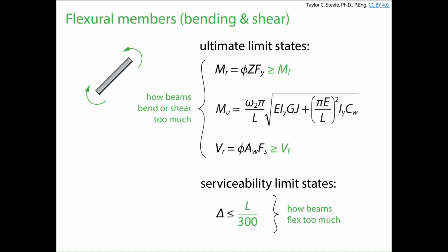So far, for the last couple lectures, we've been talking about flexural members, and it's mostly in the context of beams, and mostly, even then, we can divide it further into joists and girders. Our joists are fully laterally braced by the steel deck, so the compression flange doesn't actually want to sway sideways. The beam does not experience lateral torsional buckling. And if we have a stocky section, we can get the plastic moment resistance. If we have a slender section, like class 3, we can get the yield moment resistance. And we're not going to talk much more about class 4 sections for this course.